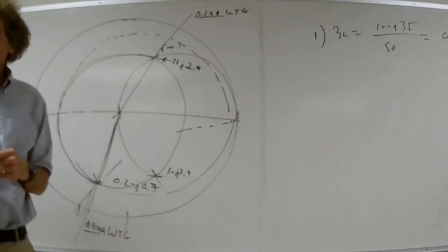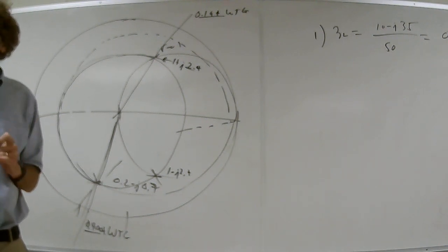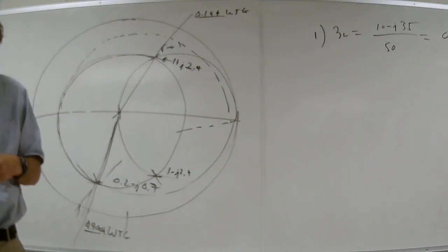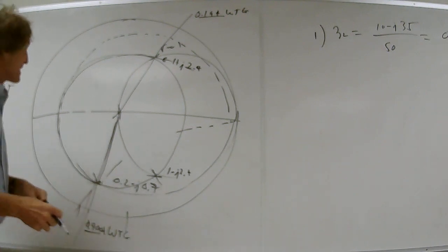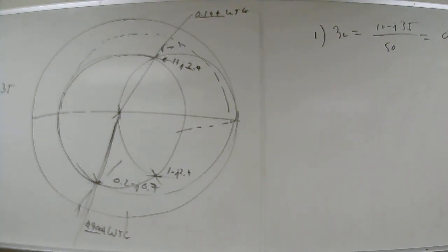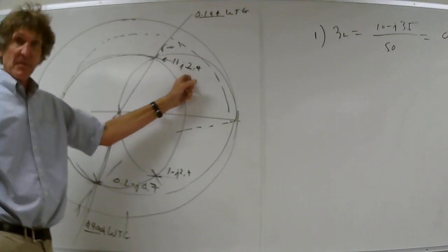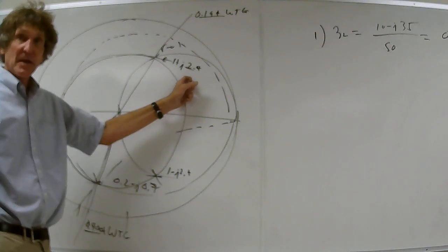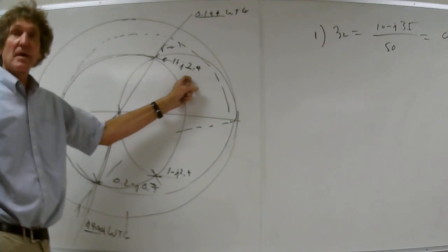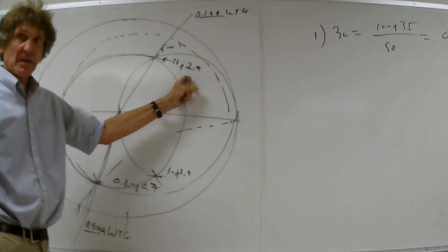So, when you get that drawn, I want you to hear me now. This is the rationale. I know we're putting a capacitor in series with it, correct? A capacitor has a minus J over omega C reactance. You all with me, class? So if we're going to use that to nullify something, it has to be a positive J something. You see how that's positive J something? That's where we stop if we're putting a capacitor in series. Agreed, class? Y'all follow the rationale behind it.